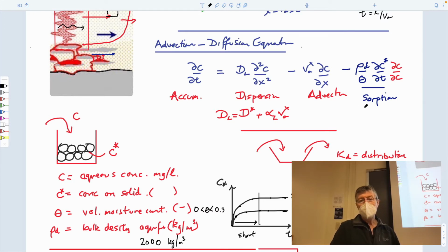And then we can multiply it through by, for now, ignore the term to the right of this, dCdt. So the amount of mass that we're losing is going to be proportional to the amount of mass that gets sorbed onto the solid, because it has to come from the liquid, and therefore it's net removed from the liquid, and it's a rate that occurs with time. And so this term here has to be the same units as this. And so clearly the concentration change with C star can't be the same as the concentration of the liquid, right? Because this is not dimensionless.